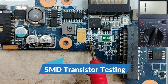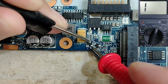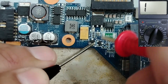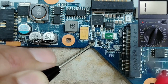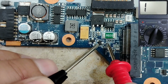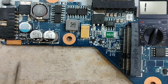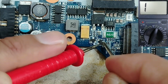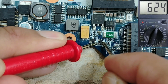Here this is the emitter, collector, and base. So for the transistor, between emitter and collector, we should get a reading, as you can see. If we swap the probes, normally we should not get anything, as you can see, nothing. Okay, the same for this one. We have this dot, which means this is the emitter. So between emitter and collector, nothing, good. But if I swap the probes, I should get a reading between collector and emitter. Let's check. I get a reading of about 600.